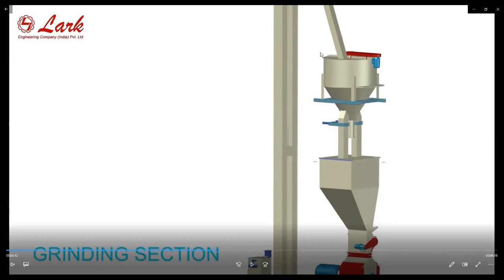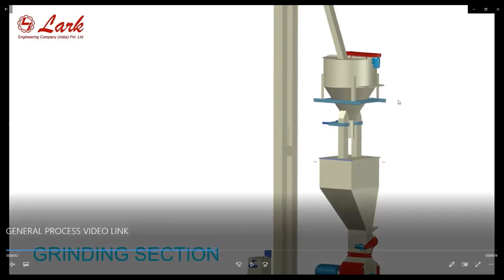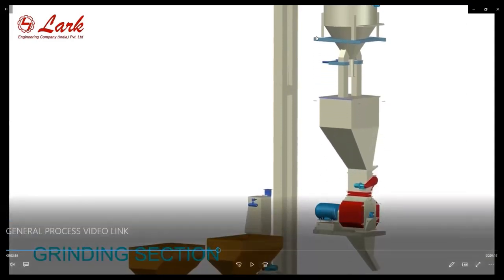And so this pre-mixing of the grains and the fiber below the hammer mill increases the hammer mill efficiency, and also reduces the operating cost of the grinding process. After the pre-mixing, there is a buffer hopper of the hammer mill, and then there is a rotary vane feeder with the VFD.